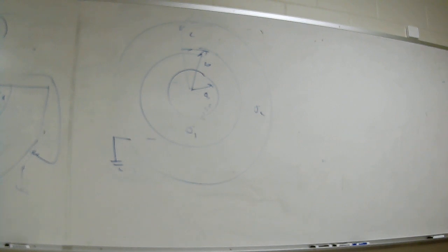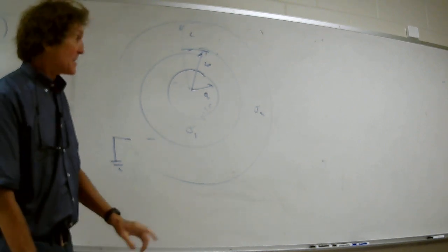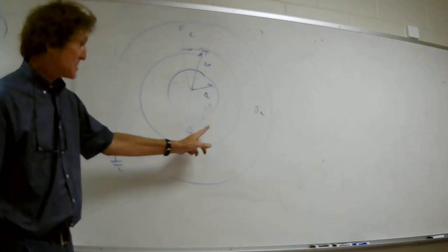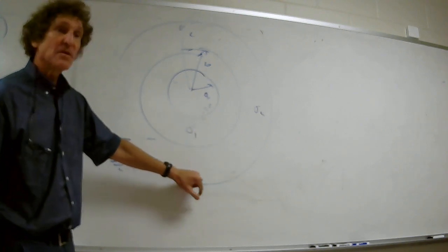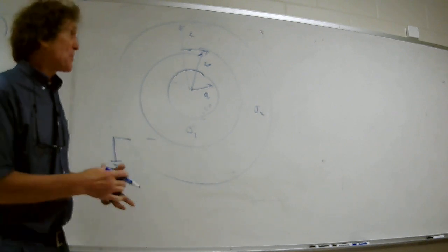And all you integrate for the voltages for the first one from A to B and the second one from B to C. And you know what? You already know what the resistance is for constant sigma, right? So from here to here, you'd put that resistance from A to B. Then from B to C, you'd put that resistance in series and add. Y'all see that? And you could go through every permutation.